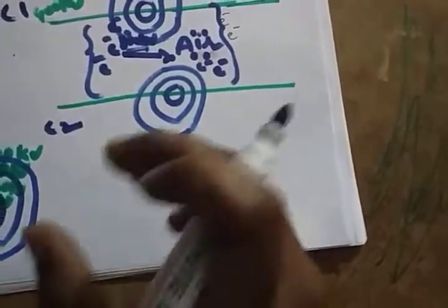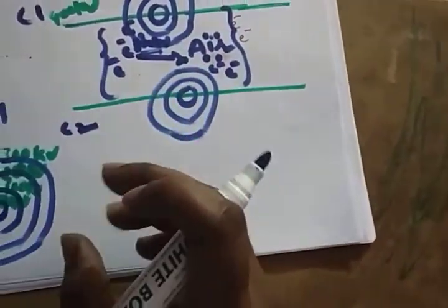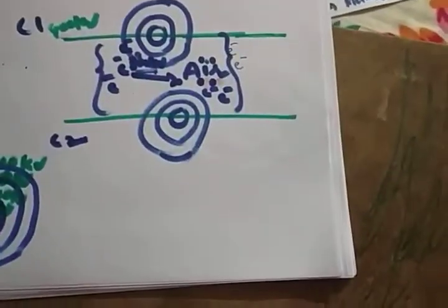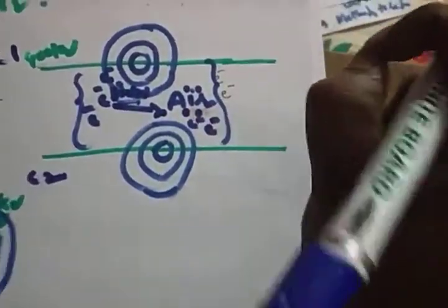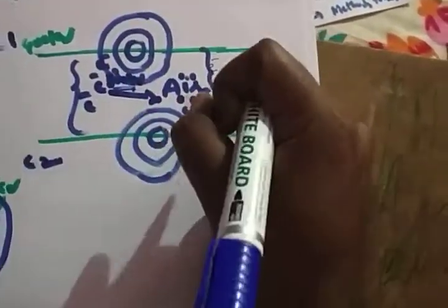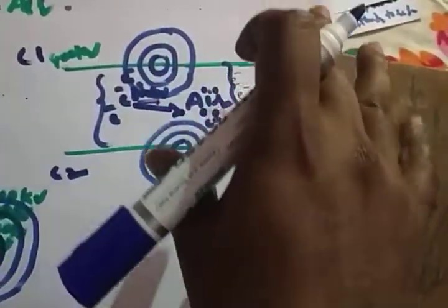And when the electrons flow between the two conductors, there will be some noise you will get. So that noise and the violet glow, and some ozone gas is also developed between the two conductors. This phenomenon on the overhead transmission system, we can call it a corona.